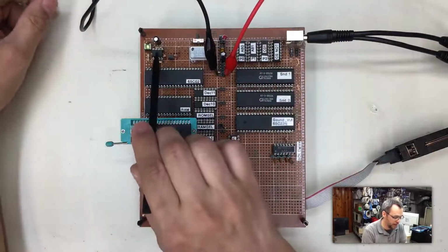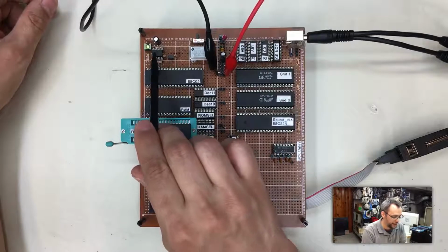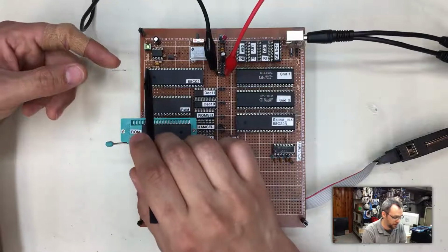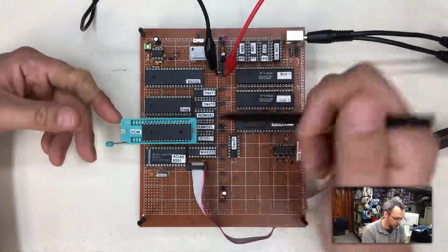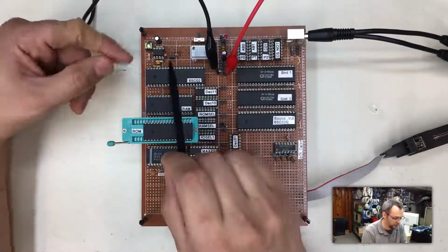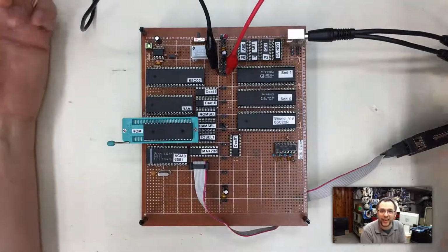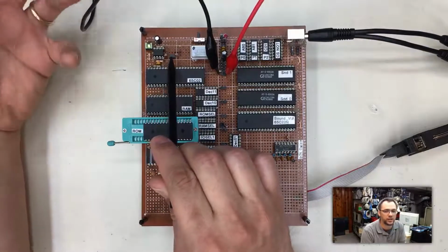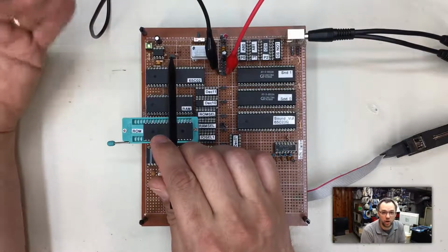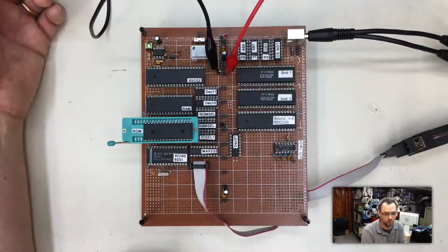The inverter inverts this line from high to low when it's active. It goes to the reset pin, which is an active low pin, and resets it. But because this is held for a really long period of time, like half a second really, this doesn't have any crazy switching characteristics. It's not turning on and off a lot, so the speed of this circuit isn't terribly critical.